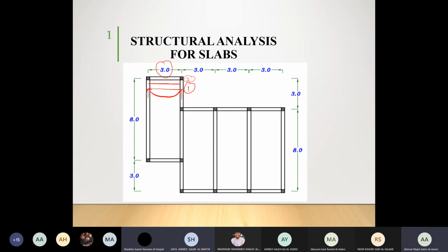Yes, Mr. Okay. Now, if I draw a strip now here, is it going to be the same as 1 or 2? No, it will be different. So this is continuous. So this is going to be my second case now. First case, it was only a single strip of slab where it has 2 supports which are discontinuous. Now what we are having now, we are having first support, second support, third support, fourth support, and then fifth support. How many discontinuous? Discontinuous are the ones outside.